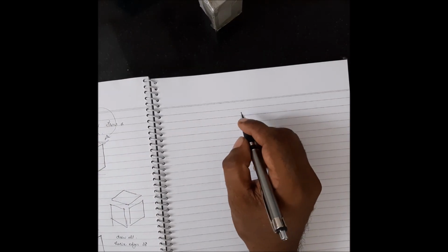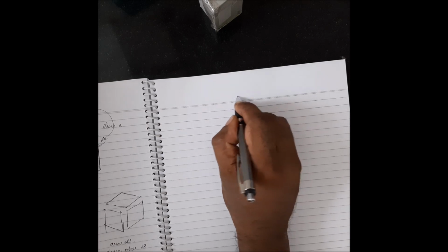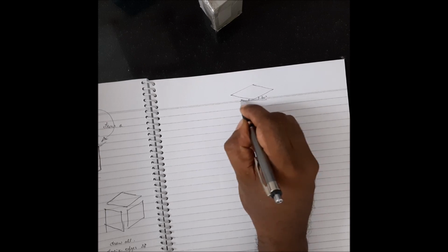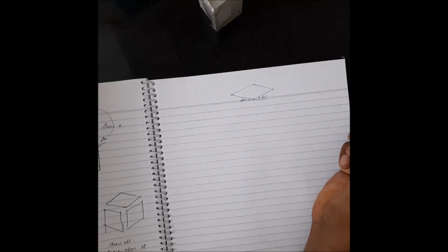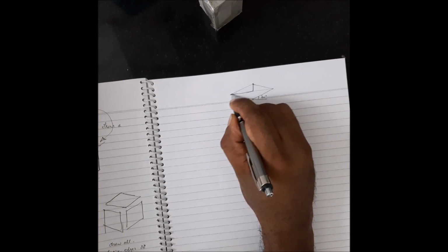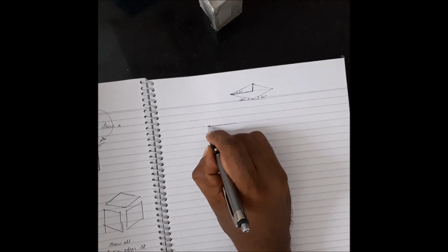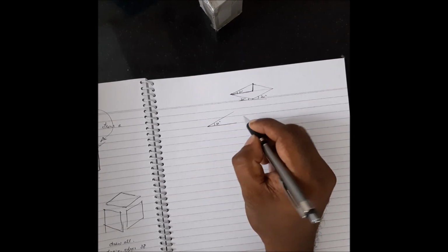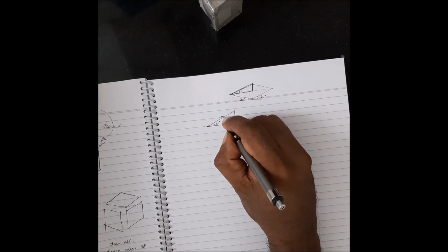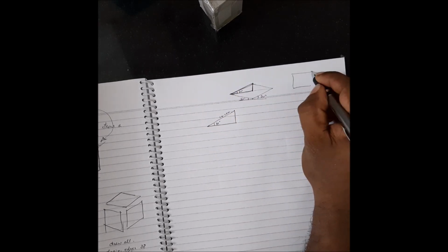To find out how much it is foreshortened, I'm going to draw the same old figure of the top plane, which is 30 degrees inclined. Now I'm going to take this small triangle right here. So this is 30 degrees. I'm going to draw a 30 degrees angle like this. Now this length is actually my isometric length. Now what is the actual length of the square? If you take a square,